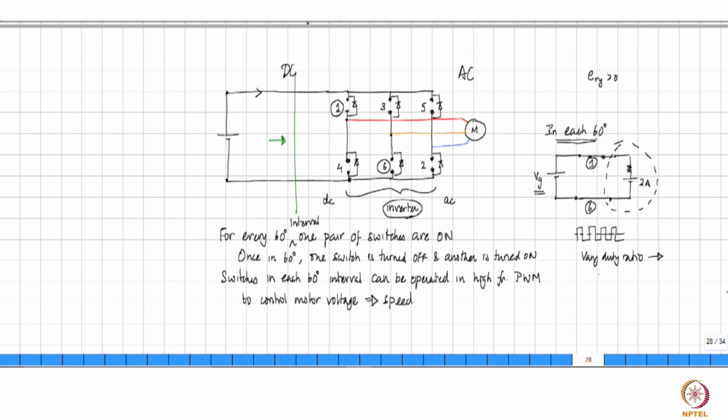Why? If you reverse the supply, you have diodes that are connected here, and a reverse supply will simply short circuit through the diodes and your whole circuit will simply blow up. Right? So it is not an option now to reverse any sign of input voltage. One has to figure out other ways of handling it.